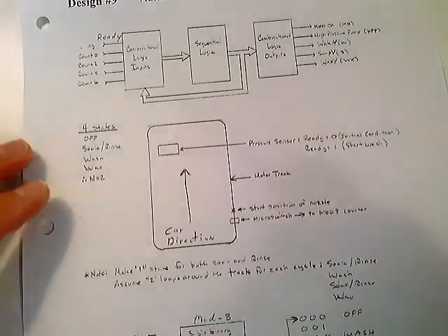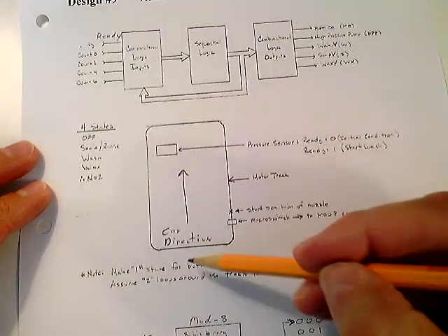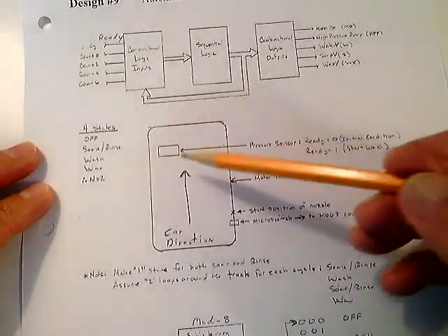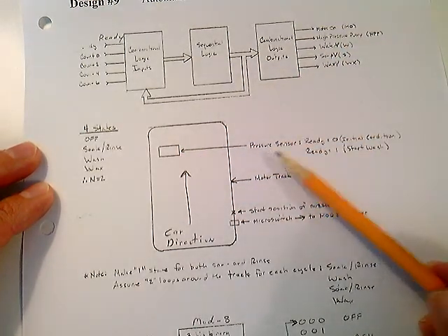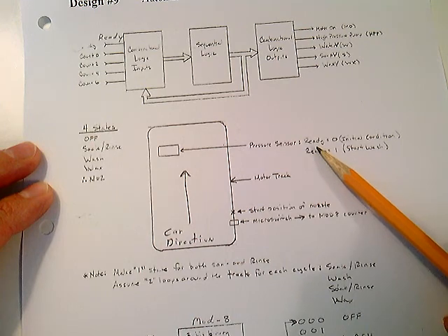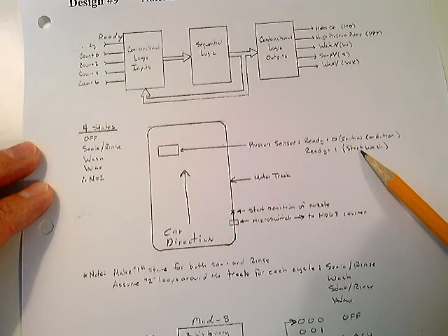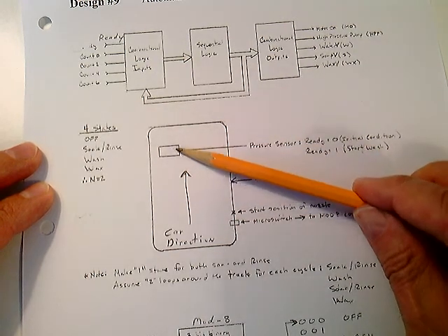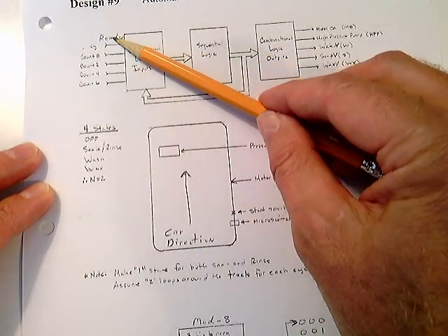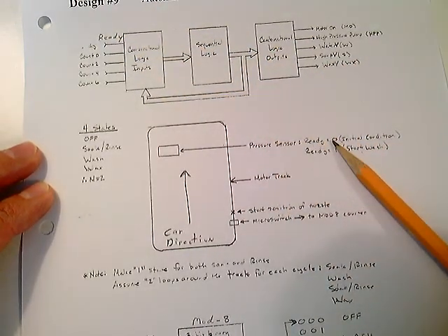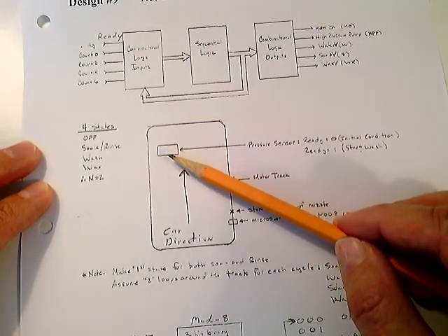So what happens? Well, I do a picture down here. You're driving your car in this direction right here, and you pull in, and the front left tire, or one of the front tires, hits that sensor, that pressure sensor. So the pressure sensor is just going to provide an input. When it's 0, you're in the initial condition, and when it goes to a 1, you start the wash. So you're just waiting for that pressure sensor to go to a 1. That's the ready signal. The ready signal up here really just comes from this pressure sensor down here. When it's a 0, there's nobody in the car wash. When it goes to a 1, your car's sitting there ready to wash.